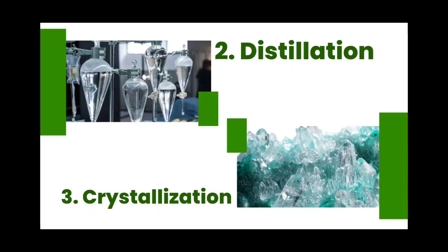The operating conditions of distillation are that it occurs under controlled temperatures and pressures. For instance, in the production of ethanol, the mixture is heated to around 78.37 degrees Celsius at atmospheric pressure. Specific distillation methods like vacuum distillation allow for lower temperatures, which can preserve heat-sensitive components. Distillation columns, often several meters tall, enhance the separation by providing more surface area for condensation.